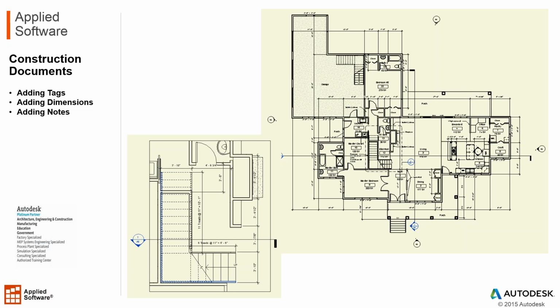Now, the biggest thing that's different about Revit from other CAD programs that you may be coming from, like AutoCAD and other programs, is that it is a single file model. And so as you work in your Revit model, everything that you do is in that one file. So as you move a wall, or delete a window, or add a window, or whatever, it's going to be affected everywhere. So it's instantly updated, so all your documents are going to look the same. And so it's really got this change it once, change it everywhere type of attitude, so that you can make sure that everything's coordinated.